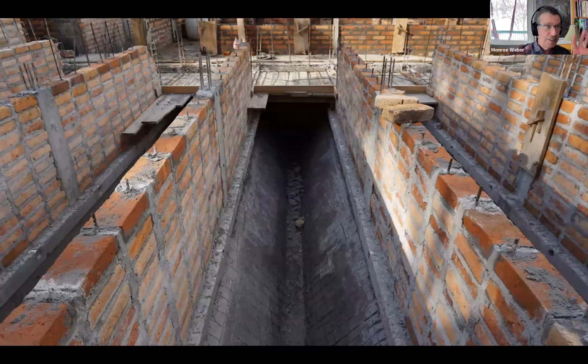So here's another view of this floc filter sed. The ledge that you see along the side here is a ledge that will eventually be used to help support the plate settlers. So the plate settlers will be sitting on that on their edges, on the sides. This platform here is where there will eventually be our system of 4 channels that control the inflow and outflow into this system. And of course, these are the dividing walls between the different units. And you can see the construction here.